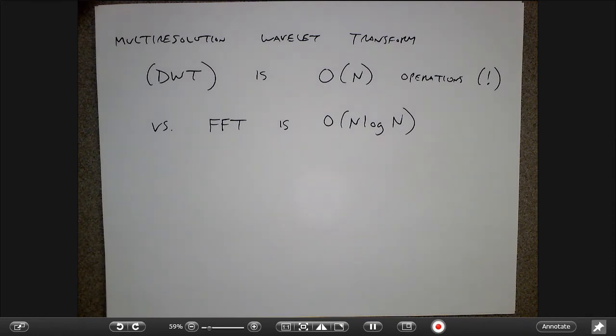So for things like communications theory, control theory, and so on, where so much of the way of thinking about a system is in the frequency domain, because we want to know what the modes of analysis of a signal are, those are places where we still want to talk about the Fourier domain. Wavelets are best, I think, from a computational point of view. That's maybe the bottom line: if I have to squeeze all the information out of a signal as efficiently as possible, then I should be using wavelets instead of the Fourier transform.